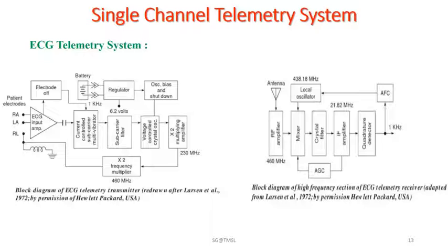And here the commonly used frequency range is 174 to 185 megahertz, with the output limited to 150 microvolt per meter at a distance of 30 meters. And special arrangements should be there, like the low transmitter battery and the nurse call facility must be there.